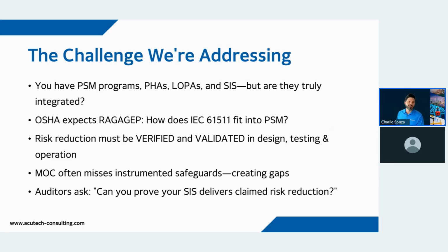That would fall under the functional safety management lifecycle. And that person needs to report back and needs to make sure that throughout the project and beyond project, but in operations, all of the 61511 requirements are achieved. So the risk reduction is true, is real.